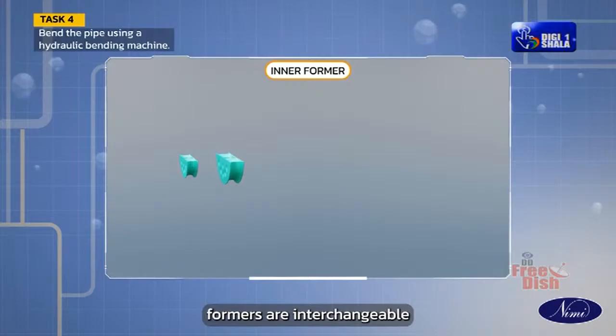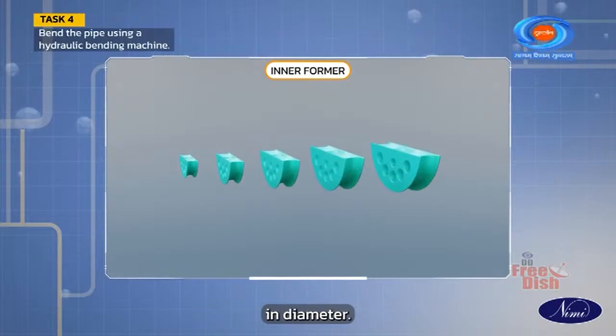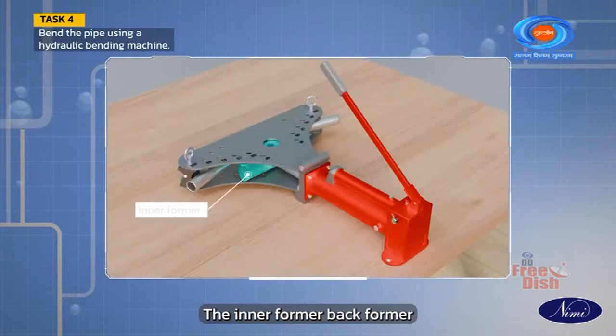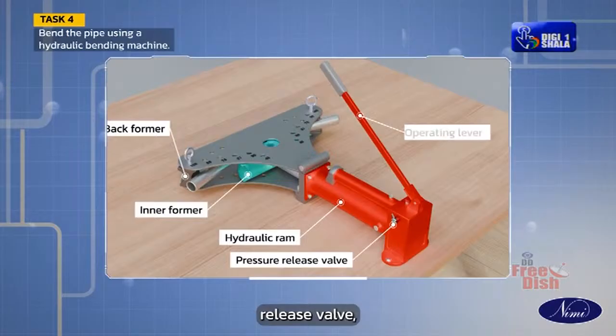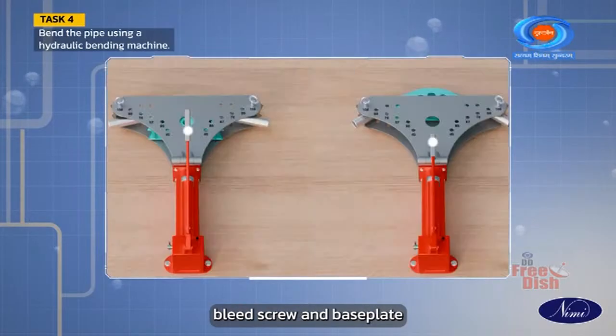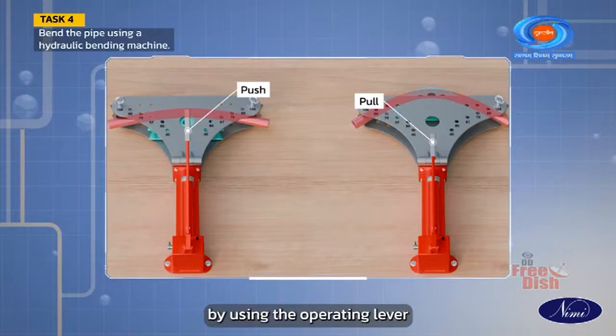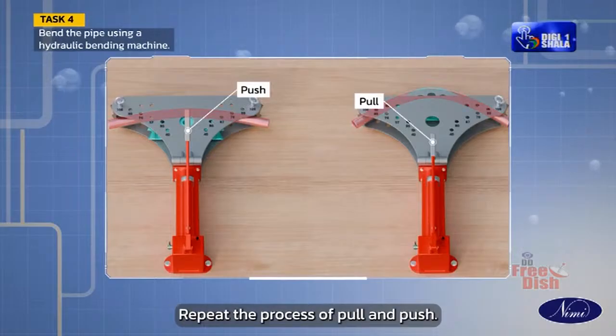The inner formers are interchangeable and can bend pipes up to 75 mm in diameter. The machine has the inner former, back former, hydraulic ram, pressure release valve, operating lever, bleed screw and base plate. Stop the pull and push by using the operating lever. To achieve the required angle of bend, repeat the process of pull and push.